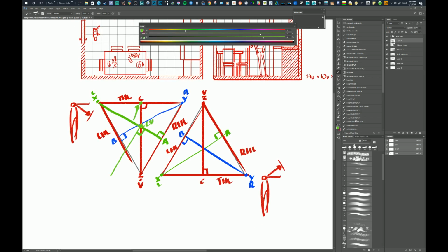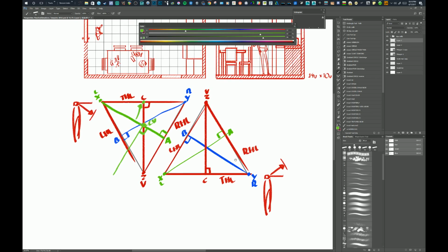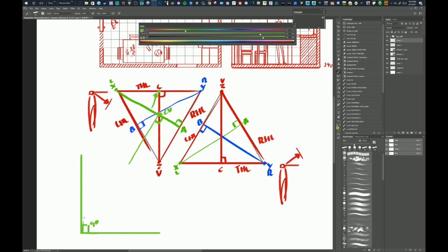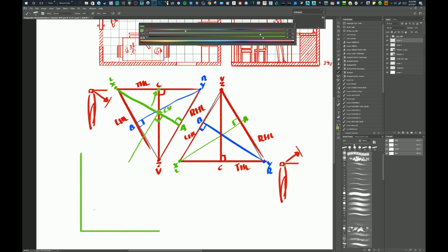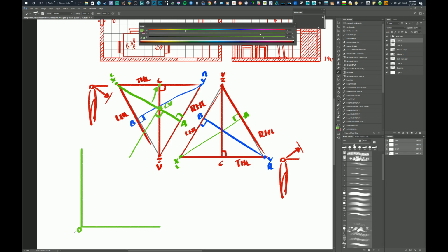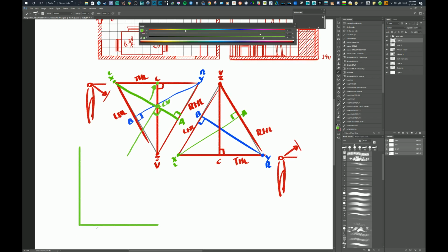Okay. Now here's where it gets a little bit tricky, and I'm going to use a little trick. We're just going to create an L shape. I use an L shape because it's 90 degrees. We have 90 degrees separation between the right and the left line. We know from 2-point perspective that this is how we actually turn objects in space. We go from the eye, wherever the eye is at, and then we make a 90-degree angle from there based on the rotation of the object.